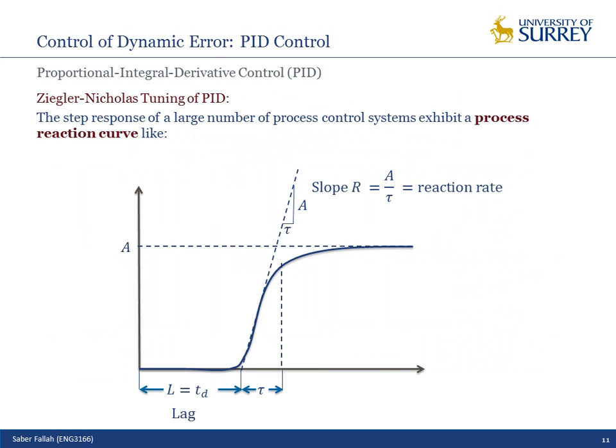Okay, when I have the PID controller, I have 3 gains. How can I tune the gains practically, not mathematically? What I ask you for this competition is the mathematical, theoretical design of the PID controller. What I'm telling you here is the practical tuning of the controller gains. In reality, the closed loop response is in the form of a first order system, as you saw from the MATLAB code example.